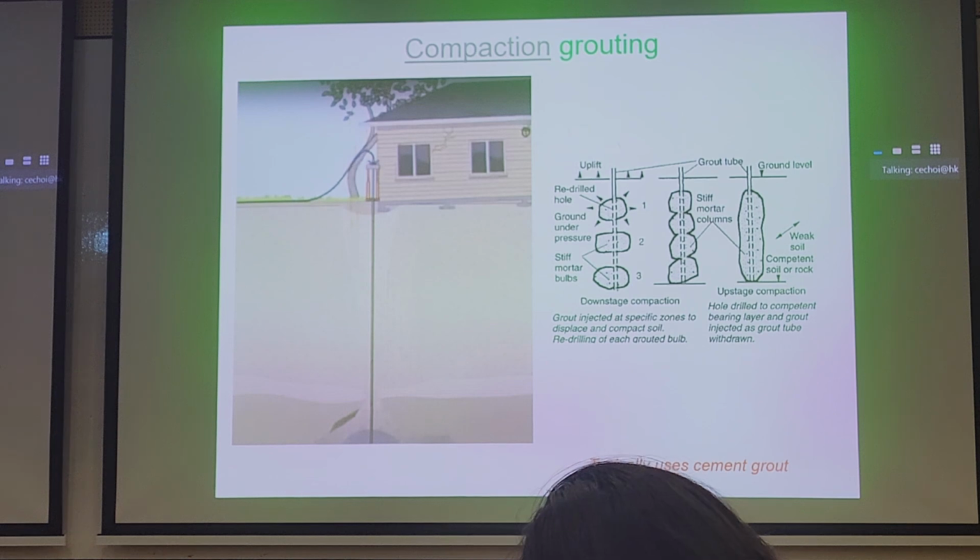So we're basically densifying this very loose soil, which is often found in faults or previous failures. You can treat this as a previous shear failure in the ground. And the soil's been sheared, it's quite loose. And we just keep on injecting the ground until we fill up this entire fissure in the ground. And then we're not worried about this house falling in.